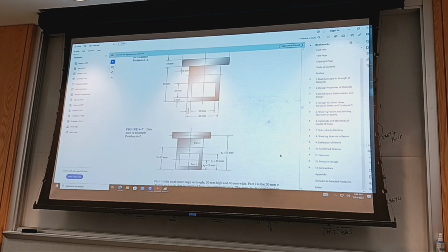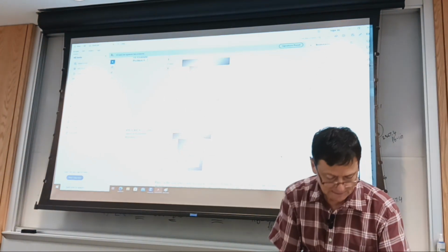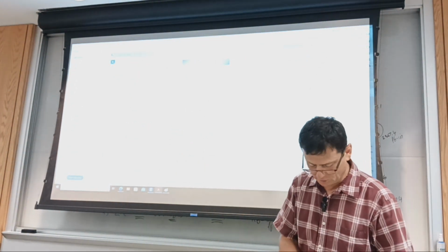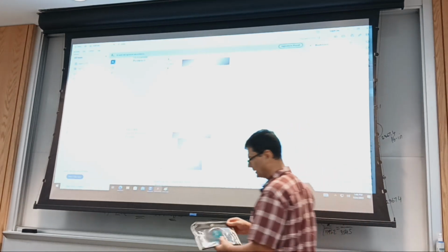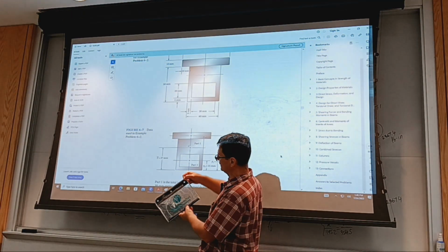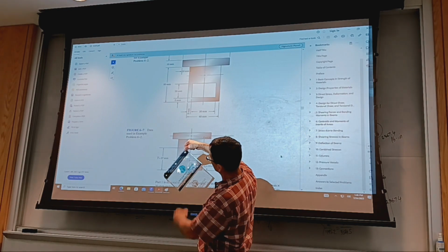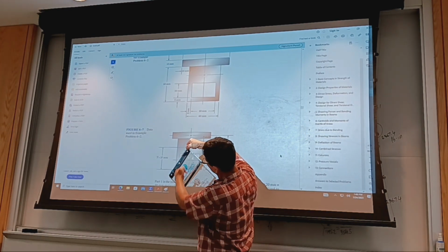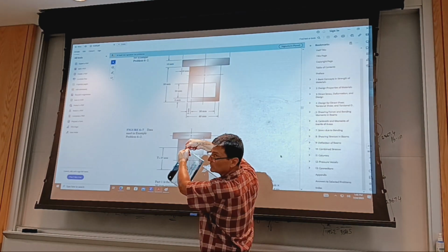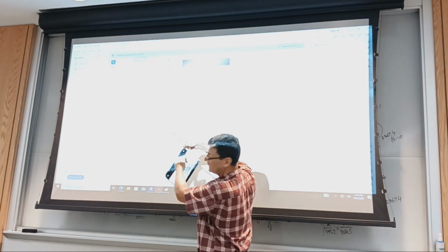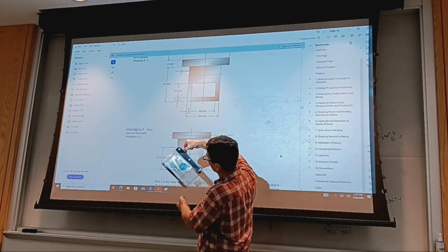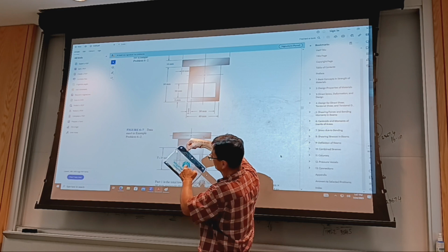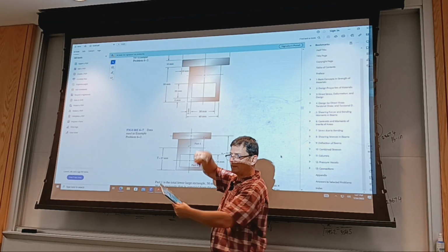There are other ways of finding the center. I'm just telling you here, maybe you've been told in statics. You have an irregularly shaped plate. You can find the centroid by hanging it from two spots. The center of mass is going to be along the vertical through the support, through the pin. You draw a line, and then you hang it from the other one. Draw this other line, and where the two intersect is the centroid. It could be any shape, any shape.